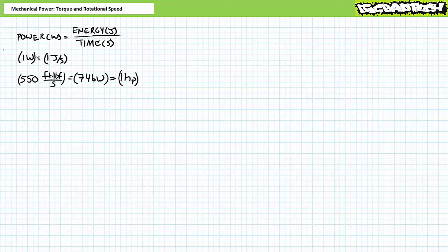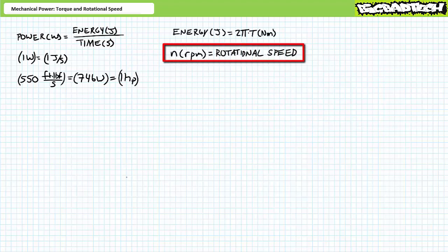Rotationally, not so much, albeit it's intrinsically much easier to understand than our earlier discussion of torque, because a rotational shaft is obviously rotating at a given speed or number of turns per given time period. If a shaft rotates slowly, yet it still exerts a constant amount of torque per revolution, chances are it's delivering less power to a system than one exerting the same amount of torque per revolution, but doing so at a greater rotational speed. The missing link in our discussion of power is this speed quantity, which some genius decided to represent mathematically with the letter N.